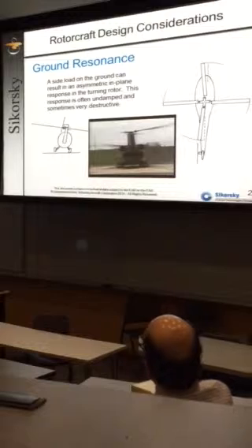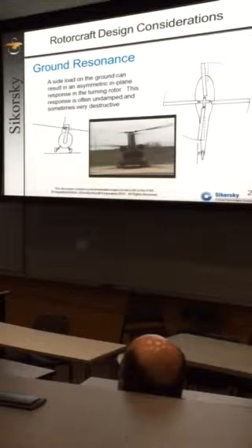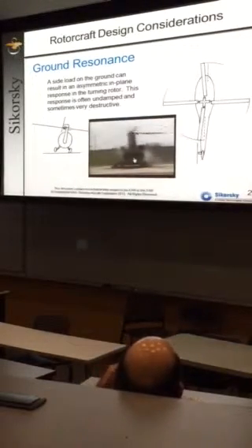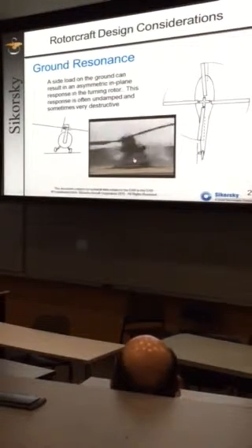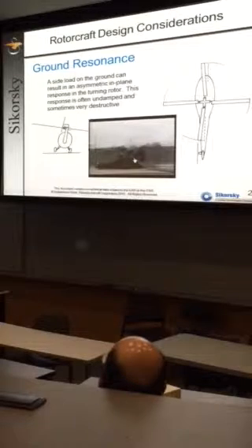Another thing we need to consider is the integration of the system. Those of you that are mechanical engineers, maybe all you engineers, probably in your early structures or maybe physics classes, learned about resonance, natural frequencies, and they probably showed you an example of the Tacoma Narrows Bridge hitting natural frequency. Well, in airframe structures, we also need to be concerned about natural frequency. This is a CH-147, and one of the things you need to be concerned with is ground resonance. So the natural frequencies of that aircraft, as it starts to react with the proximity of the ground, is something you need to account for in design, because it can literally whirl itself apart due to ground resonance if you don't properly design for those natural frequencies.